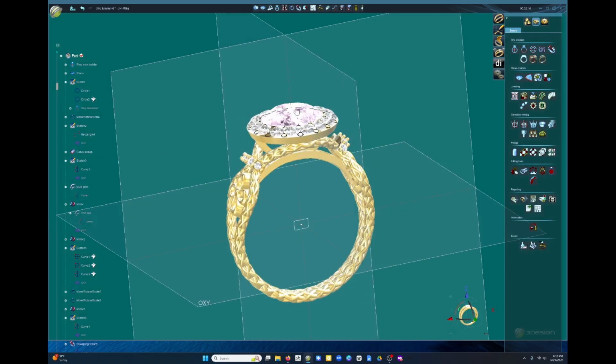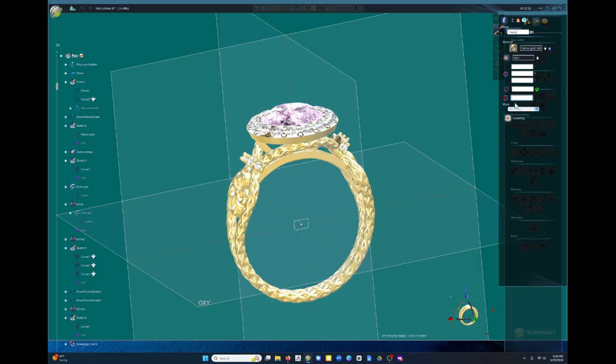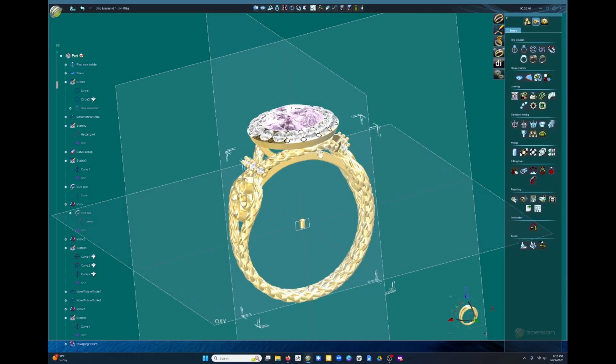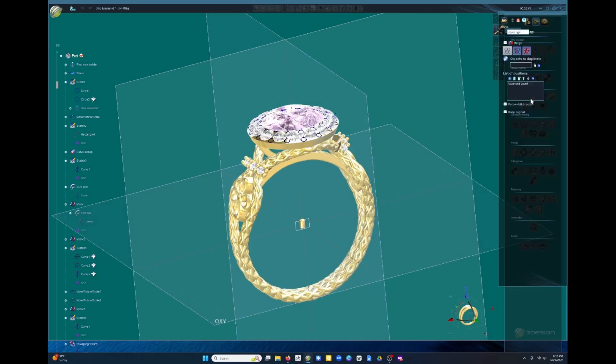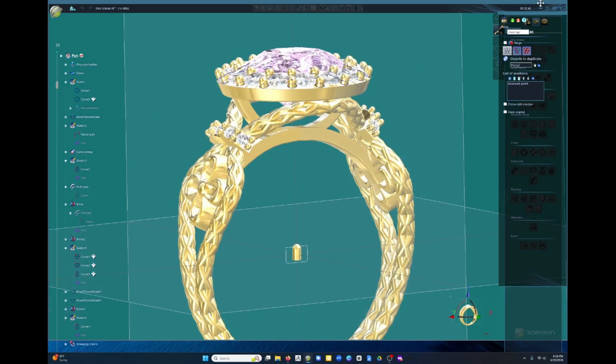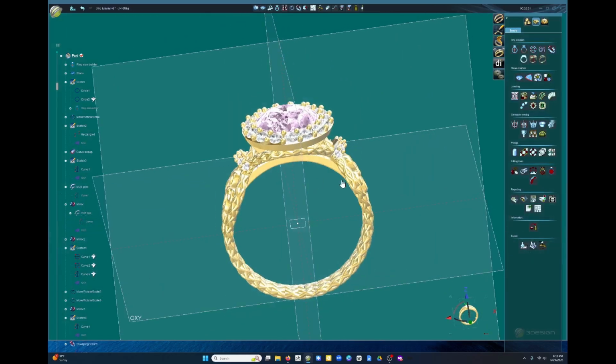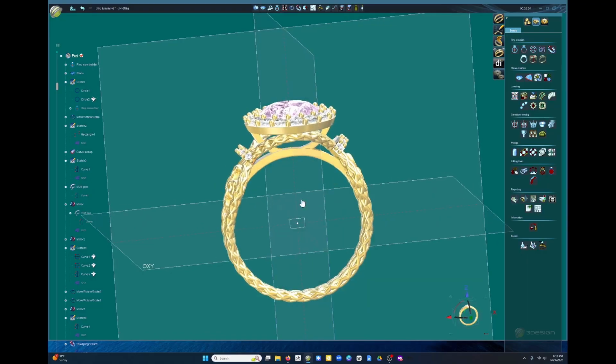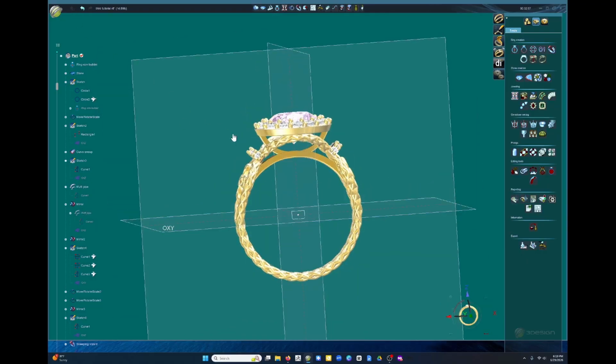And I'm gonna make another prong for this little one, because I want a little bigger. So I want to round 1.2 millimeters, 0.7, and we're gonna do minus 0.4. You click on the pavé, jeweling, and you're gonna duplicate this prong. Very nice, very high, nice height. Everything is good, perfect.